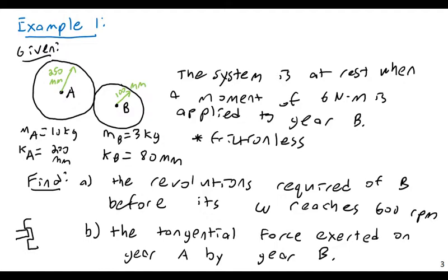And if you're not careful, when you're working with systems in physics, you're going to assume that the materials are non-deforming, that they're rigid bodies, that they can effectively take infinite force. But in reality, all real systems can't do that. So if you're actually designing an engine that is transmitting large amounts of power via gearing, then this becomes one of your primary design considerations: just making sure that the forces, and in turn the stresses in your gears, do not exceed an allowable value.